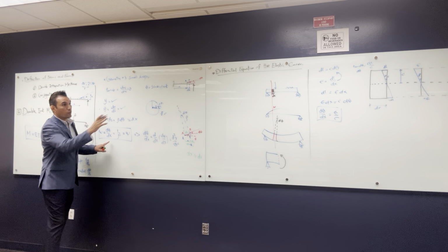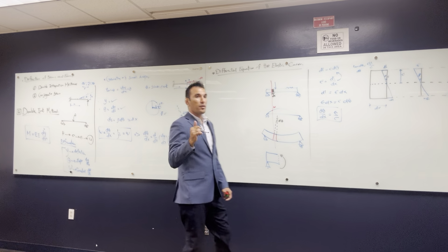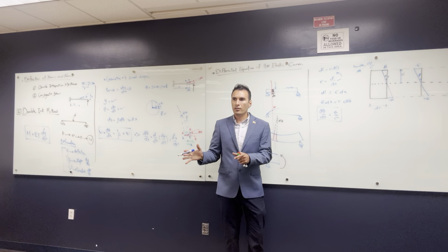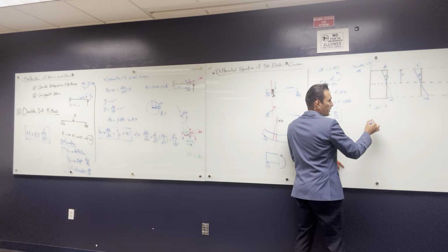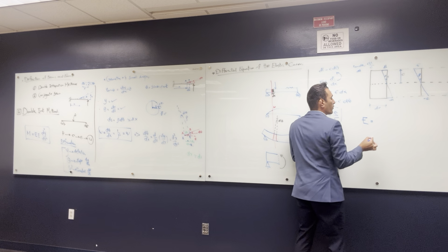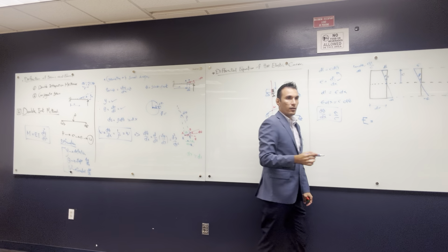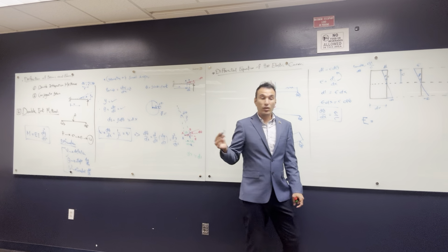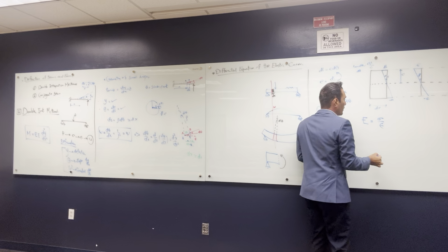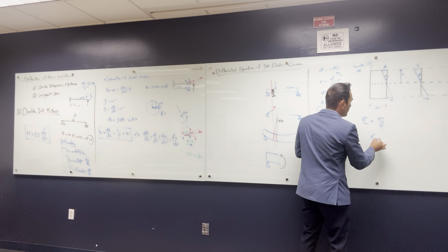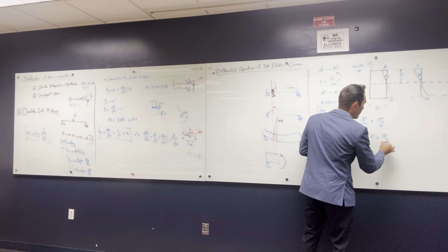d theta dx. We're gonna keep it like this, but let me remind you, do you guys know Young's modulus? We use what symbol to represent Young's modulus? E, right? Okay, what is the value of Young's modulus? Stress over strain. Stress over strain, sigma over epsilon, right? So if I wanna say epsilon, epsilon is gonna be equal to sigma over E.